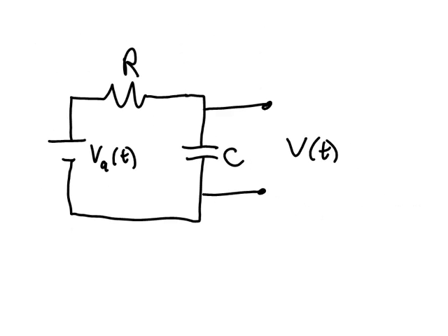Here I'm showing an RC circuit. What information about this circuit would we need to know at any given time to define the output voltage? We might need to know the current in the circuit. And we might need to know the derivative of the current. Or perhaps we need to know the integral of the current. These things are neither the input nor the output, but they are what we refer to as states of the system. Things that, if we knew them, we would define the output relative to the input.